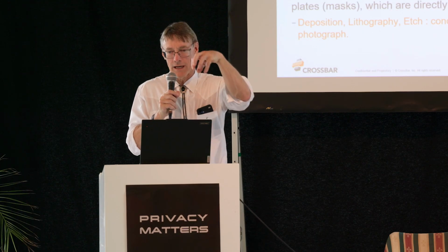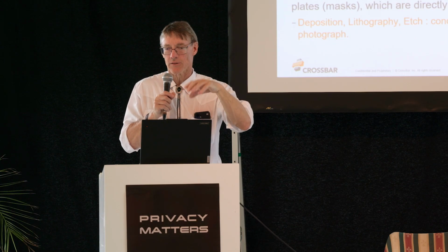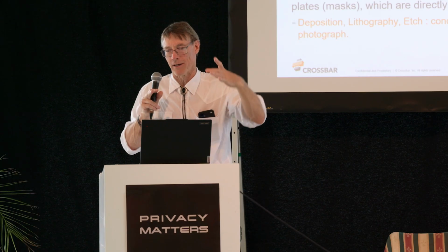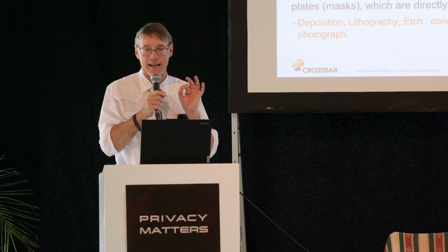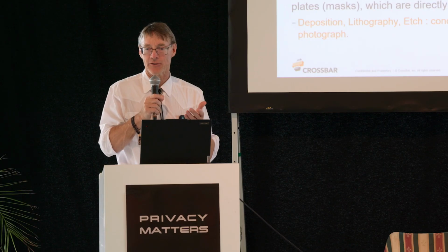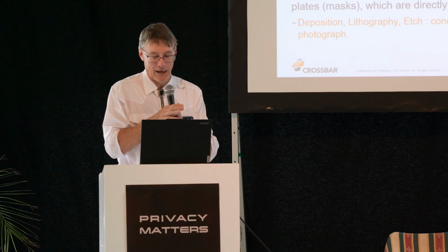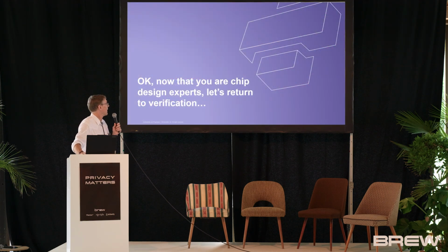So when the wafer comes out, you have to do what's called a circuit probe and probe all the logic and see which chips are good and which chips are bad and map them out, because you don't want to put a bad chip on an expensive board and then have to throw away the board. So these test circuits absolutely are an attack surface. They can look into the memories, they can read the logic, they can manipulate. So you should be very curious about what's there, when are they disabled, how are they disabled. That's not the subject of this talk, but that's actually very relevant to security.